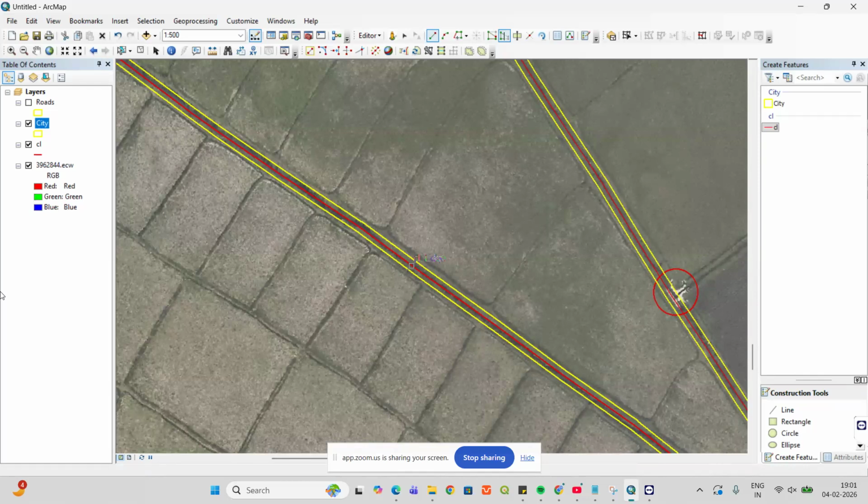So in this case, we fly it with respect to the existing ground level. So when the ground rises in altitude, the drone also equally rises, with the help of the terrain sensor. That will be fitted on the bottom along with the camera, along with the payload, at 90 degrees towards the ground surface. So when the ground is 1 meter up, the drone automatically moves 1 meter up in order to equalize the height of the drone with respect to ground level, not with mean sea level.